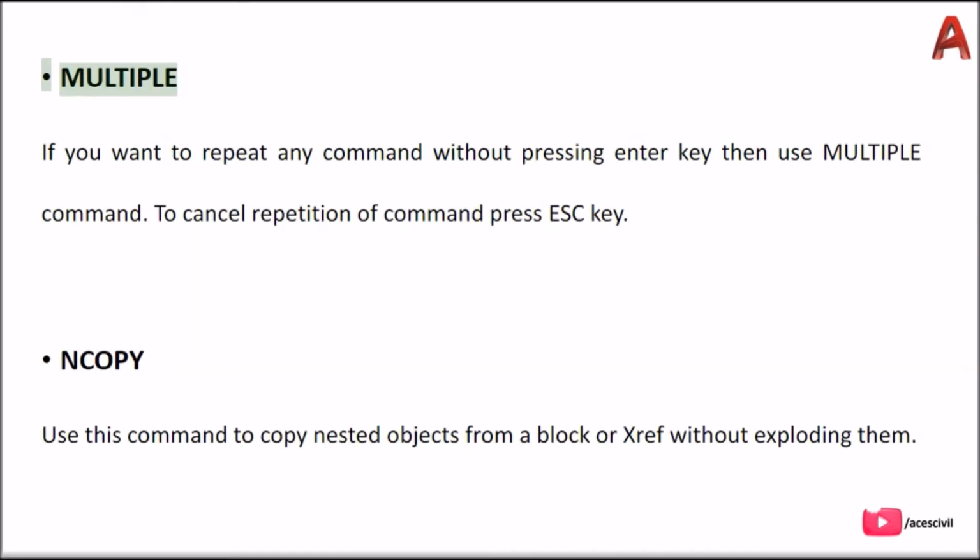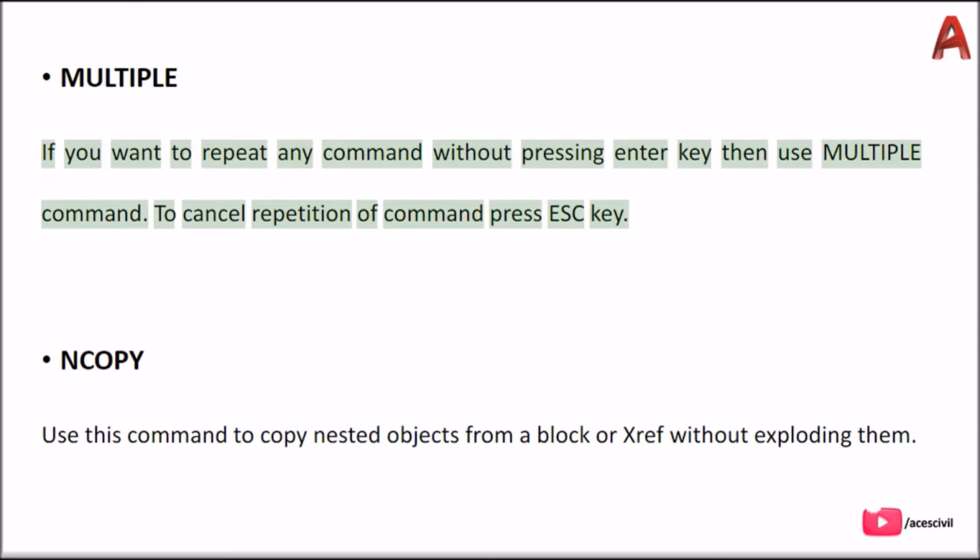Multiple. If you want to repeat any command without pressing the Enter key, then use the Multiple command. To cancel repetition of the command, press the ESC key.